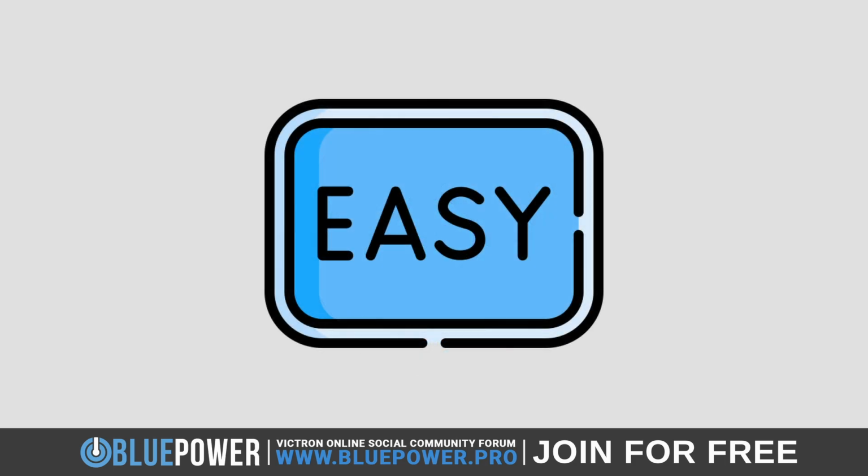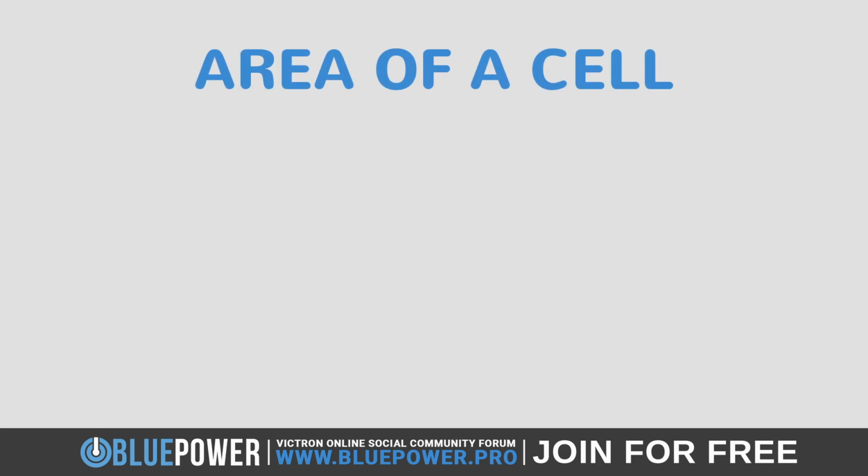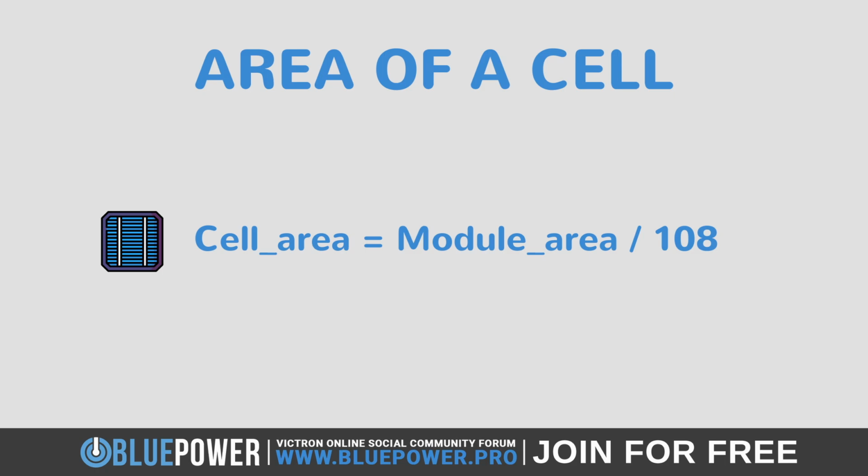Fortunately, this is quite simple, as we have done most of the work already. First, we need to see how many cells the module has, as well as what the width and length ratio of these are. The spec sheet and provided module diagram give us clear information on this, stating that there are 6 cells along the width of the module and 18 along its length. This comes to a total of 108 cells, also specified in the spec sheet. Now, in order to calculate the area of a single cell, we simply divide the module's total inner area by 108, thereby excluding the metal frame.